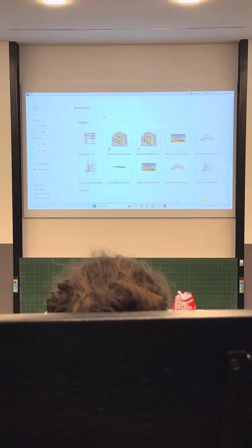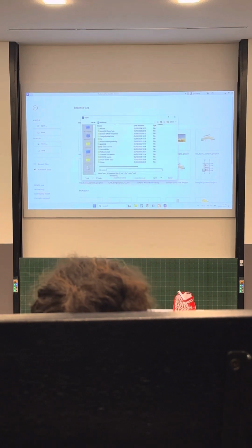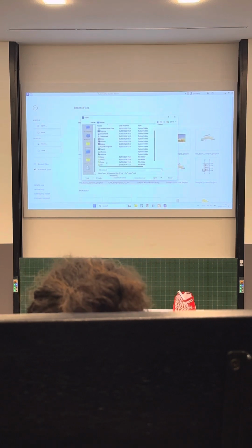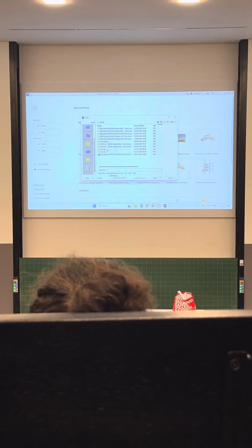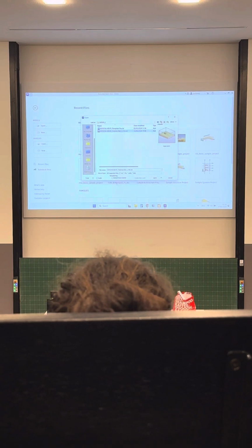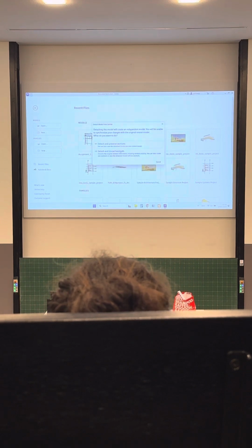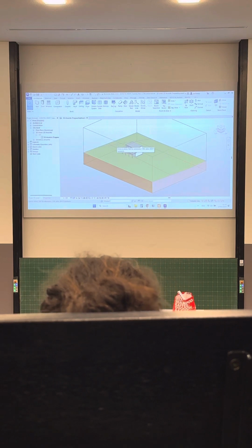Okay, coming up into the Revit, you go to Models and Open. I'm going into my one folder of Sophistic, and yeah, here is the RVT file. And to not have this error, you have to detach it from the central one. So the error should disappear now. We can try it and preserve the work sets. Yep, and now you have a model.